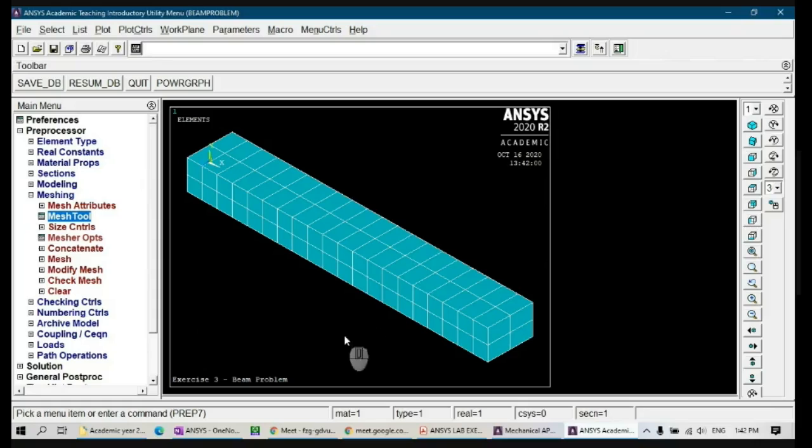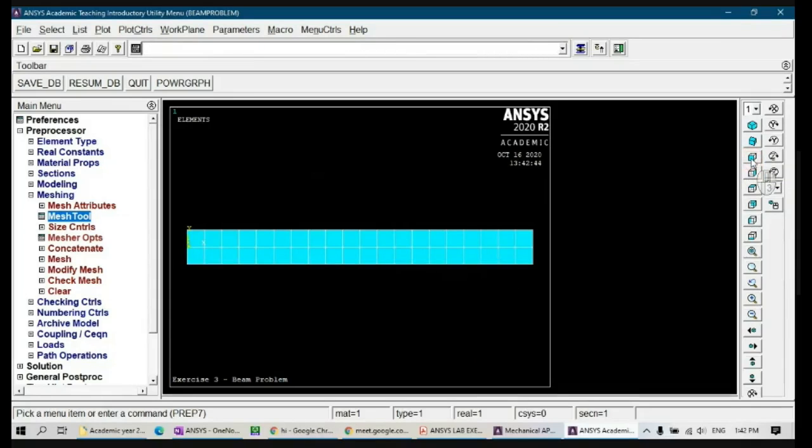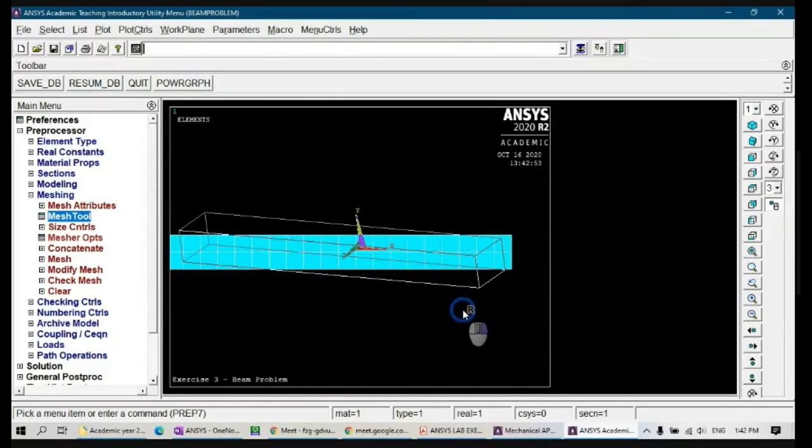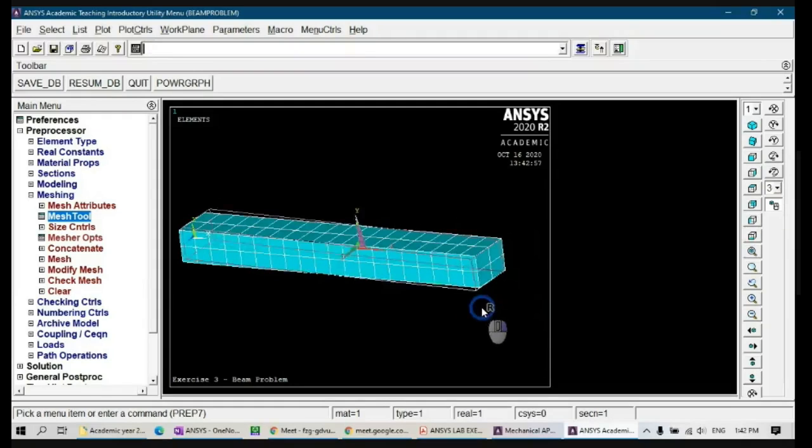Yeah, it is wrong. Actually this side should be 0.3 and this should be 0.2, so this has got swapped. This is what I said: only when you verify these things can you see the difference. When I look at the front view, it looks like this. If you don't have the correct view, you can also use this dynamic model mode. You can click and drag, and with right click I can see the rotation. I can rotate it.